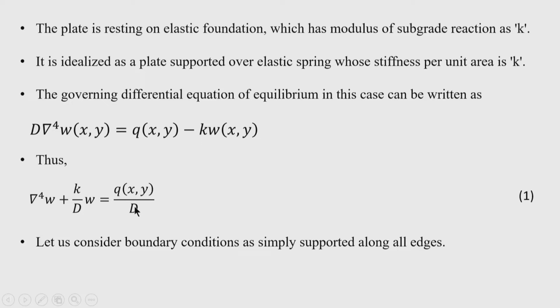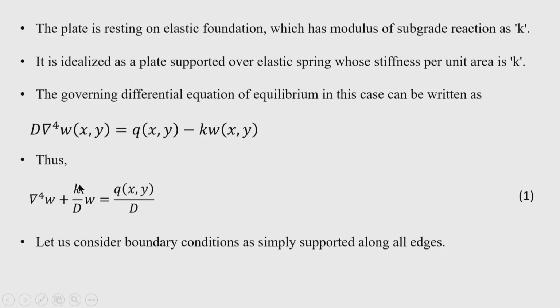Now, here one thing you should note is that the thickness of the plate is uniform throughout the area, and also the soil stiffness, that is the subgrade modulus, is constant. But in some problems it may vary, then K will be a function of x and y. Similarly, if the thickness is varying with the space variables x and y, then you will get this D as a variable in the differential equation.